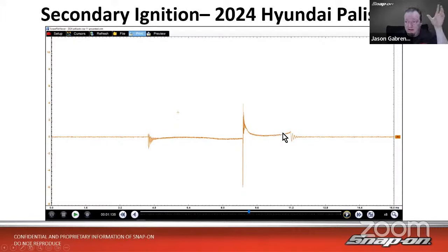It says it's meant to measure burn time is really what it's meant to do. But I definitely could see if it was going lean or rich or whatever. I think I would be able to get enough detail out of that pattern. It was just something kind of interesting. I hooked up to it for the first time, sight unseen, not knowing what to expect, and didn't get what I expected. And that happens sometimes, hooking up to cars that you don't really know how they're going to look. And then you look at it and say, oh, okay, that makes sense, how the pattern is. But yeah, it's kind of interesting information. So that's how you would see it using that COP11 adapter.